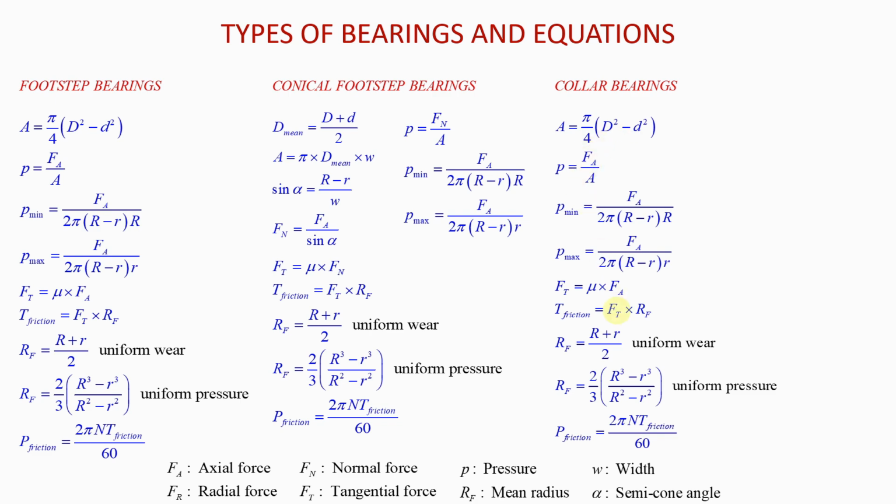So in these equations for the collar bearings, the axial force that you have here, okay, is actually the sum of axial forces on the collars, okay, very, very important.